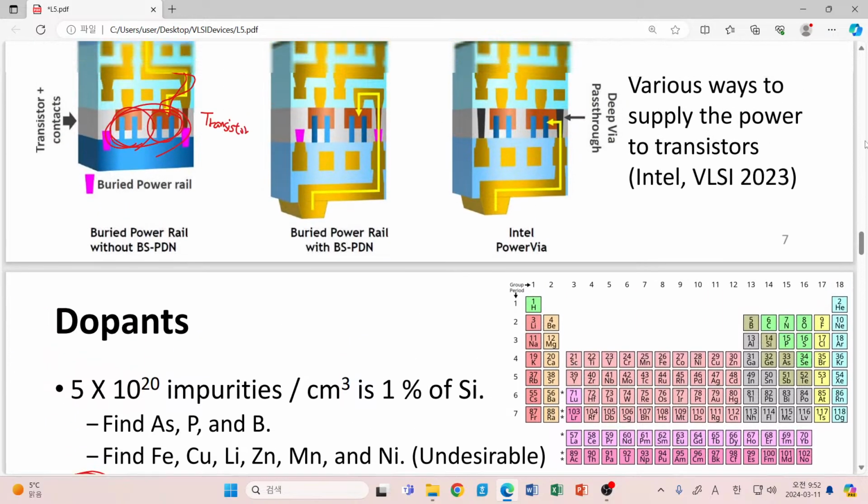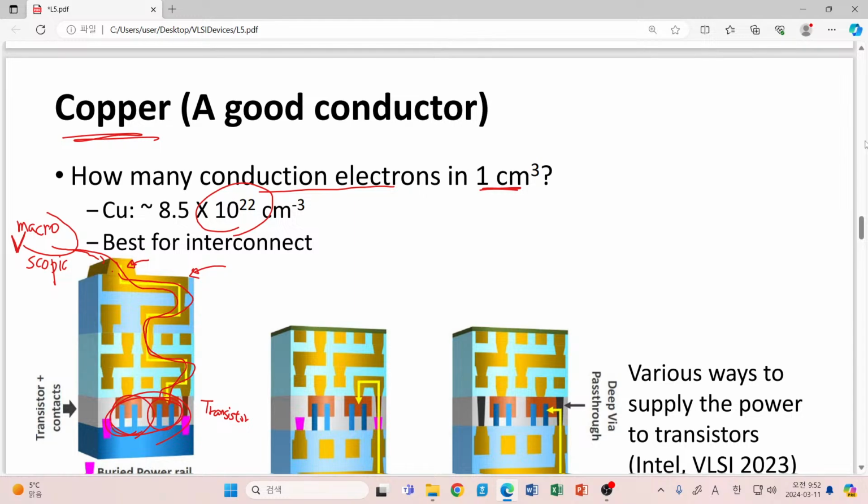So anyway, now let's come back to this copper. It is certain that when you introduce copper into your silicon crystal structure, it introduces certain levels, and these levels are not very close to the valence band, but located somewhere far away from EC and EV, and they act as a killing factor for our VLSI devices, so we don't like it.